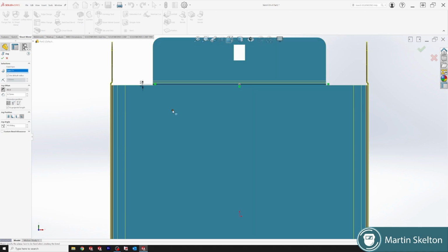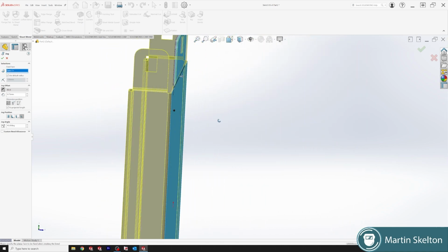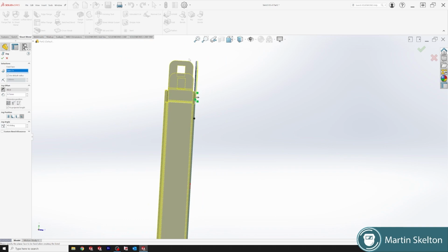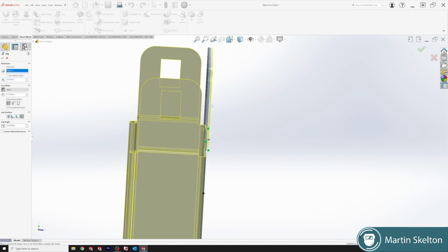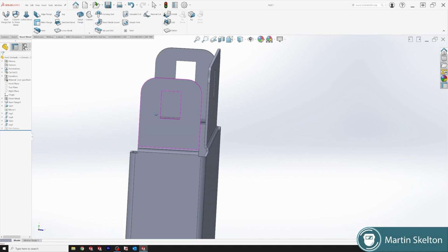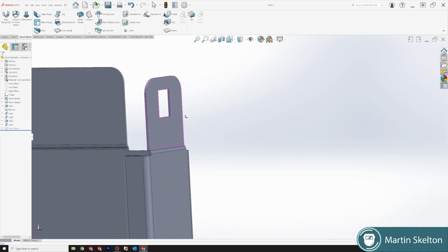This is our fixed face. And we're pointing down, but don't forget to change the default radius. It just tightens it on that point. We need it on the inside. So we click back. This flips the direction. We click OK. That's your jog feature for the inside.